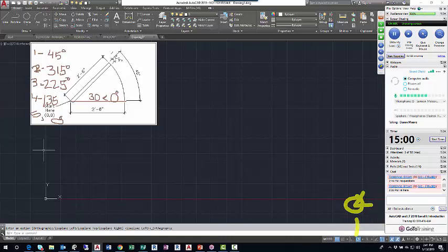So let me do this once. This door is 30 at its widest. It's 1.75 at its narrowest. And I'm going to use these angles. I'll go line. Just like with the window, I'll type in my first point, which is 0,0, enter. And then I'm going to move my mouse around until I see what I mentioned before as being a laser beam. That's called a tracking vector.